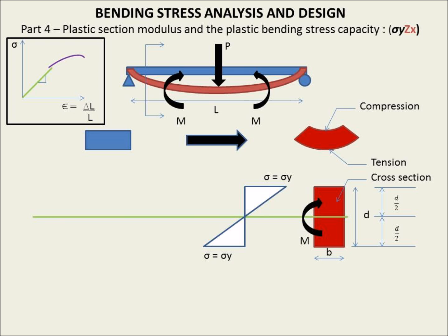We have reached the yield point, and tensile stresses at the bottom. And as you go from the compression to the tension, positive to negative, if you will, we cross zero, and the zero point is called the neutral axis. But notice, however, that only the top and the bottom part of the beam has reached yielding. The top part in compression and the bottom part in tension.